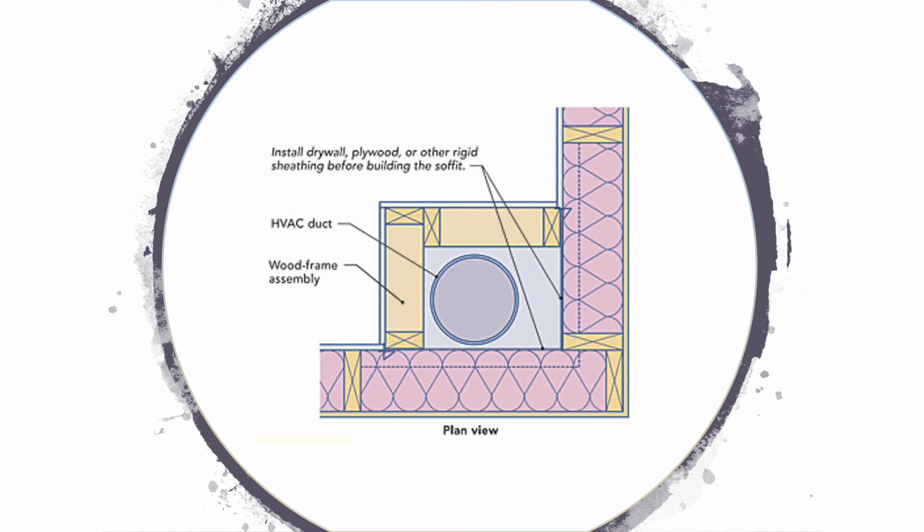Chases and ductwork and walls. Here you have an HVAC duct with a chase built all the way around it. You'll see the insulation around it. These walls here are probably insulated as well. When you get water in the middle of that chase duct, you've got to figure out how to get that water out. You may have to drill holes in there to get that out.